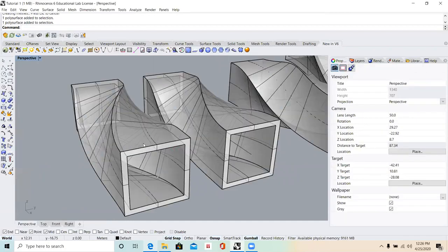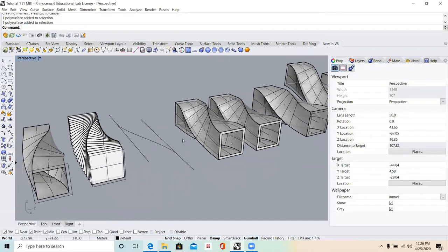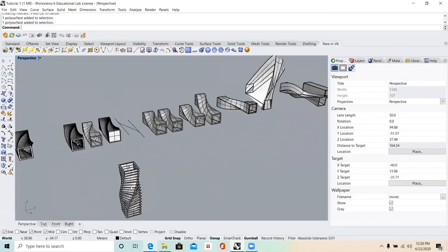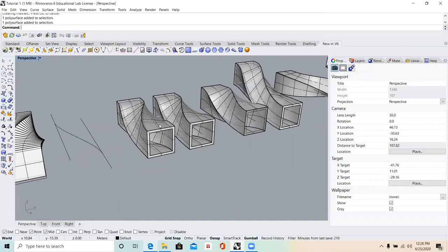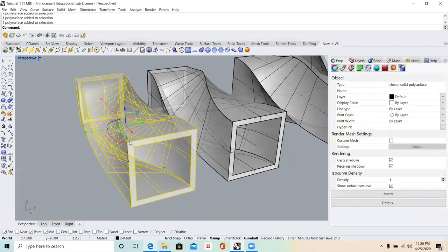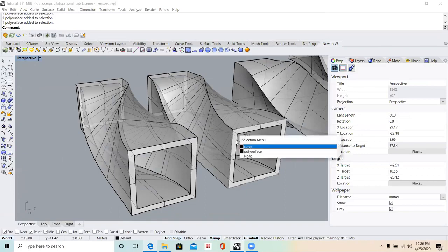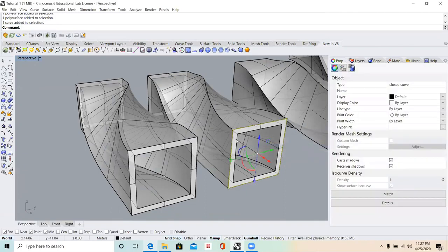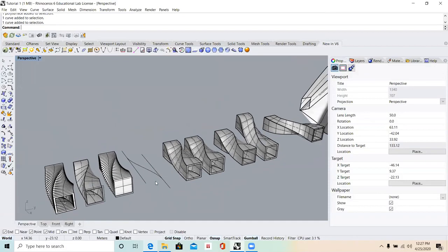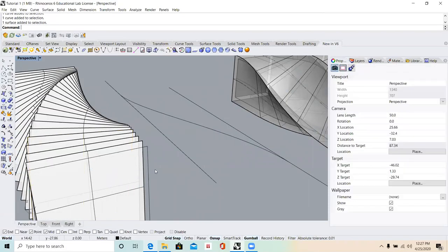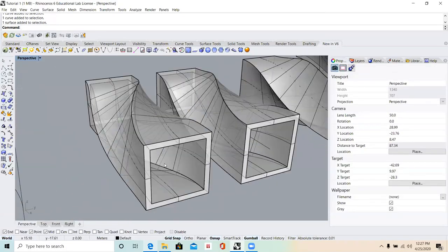Now you want to contour, because what we're trying to build in the beginning is the outside form. So you want to make sure to contour. If you only extrude the outer surface and not the inner surface, you're going to have full plane contours. But we want the inside to be hollow, right? So how do you do this?